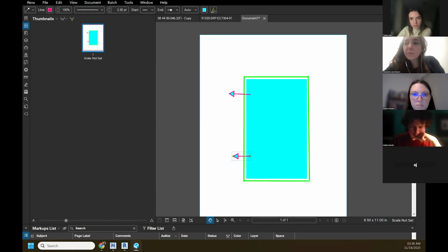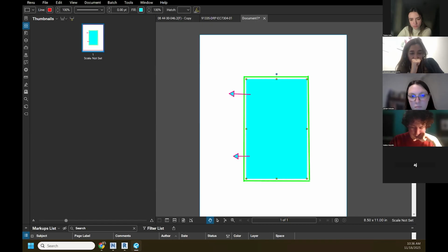The confusing thing for me is the transom. For me, the weight of the glass is going into the transom, and there are two fasteners here, and it's put on a shim pack, so it's sitting on the ground. So to me, the full gravity load of the glass is going into the transom.